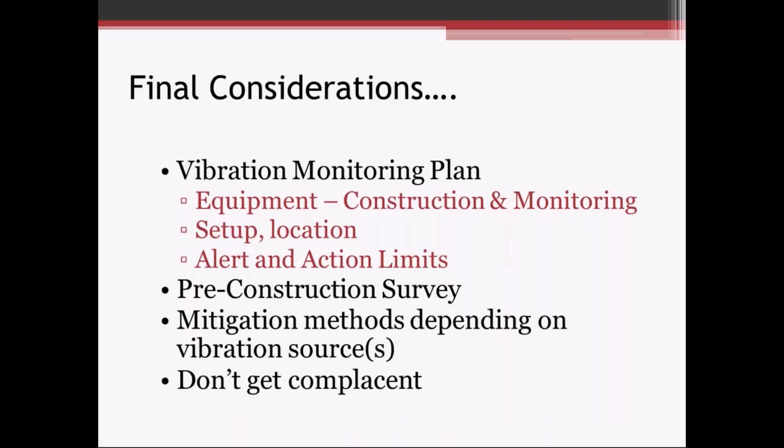So some final considerations. I mentioned the vibration monitoring plan. Very important. You want to identify the equipment, not just the equipment being used on the project, vibratory hammer for sheet piles, or a diesel hammer or something like that for the H piles being driven on abutments or foundation or something like that. But also the monitoring equipment. What type of monitoring equipment are you going to use? How are you going to set it up? Where are you going to set it up?